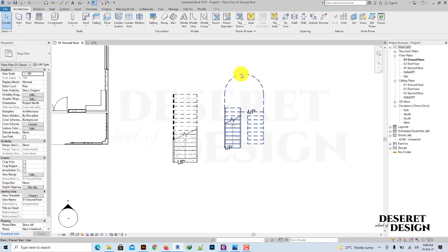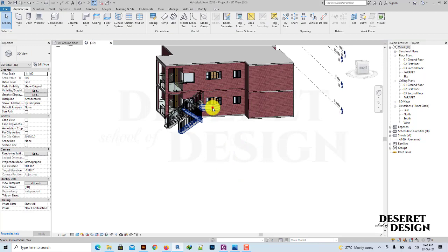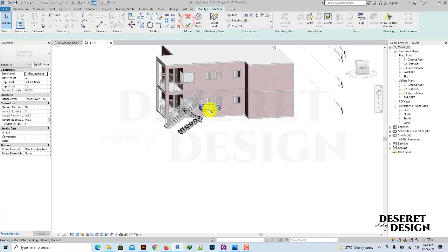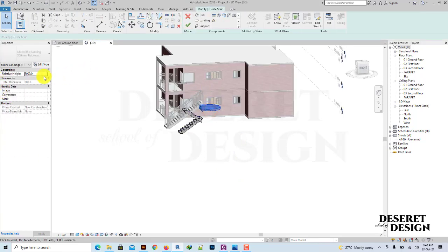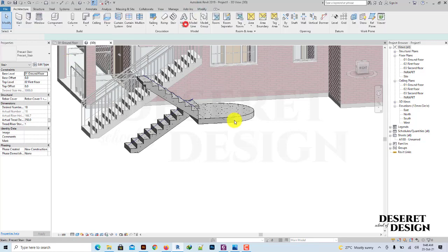Alright. So this landing is what we put inside Revit. So we'll select the landing, edit, select the landing and give it a height of 1,005. Right? This is what happens if you decide to sketch. Revit will sketch it at the height of the wall. So you have to bring it down to the middle of the stairs so that it fits in its proper place.